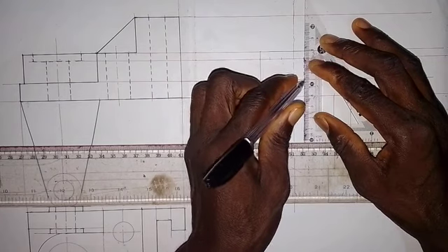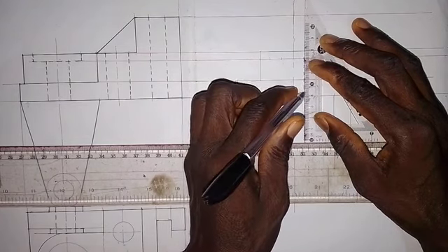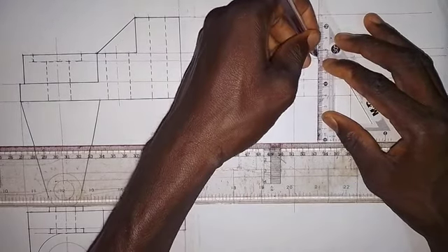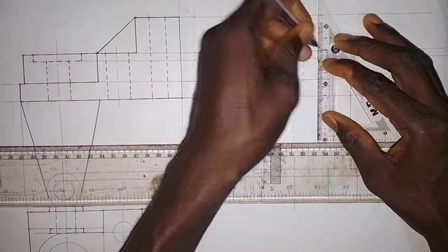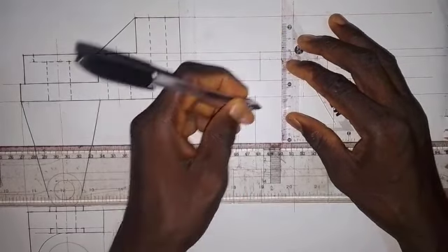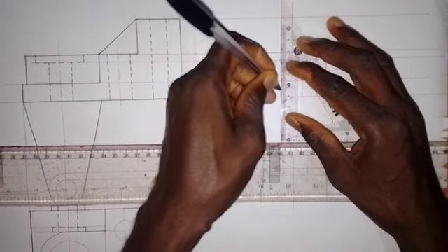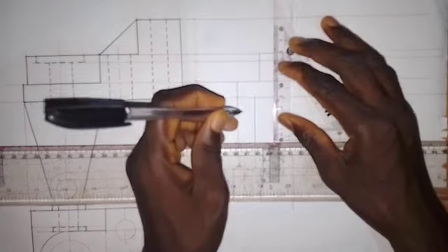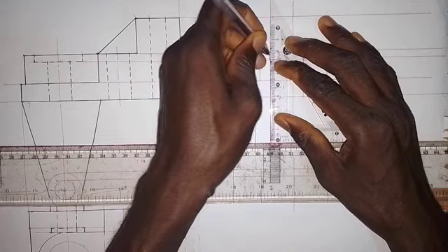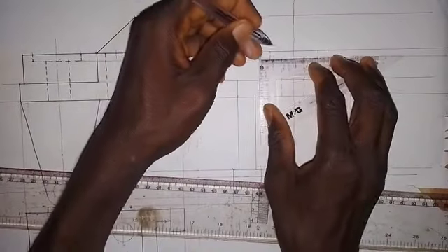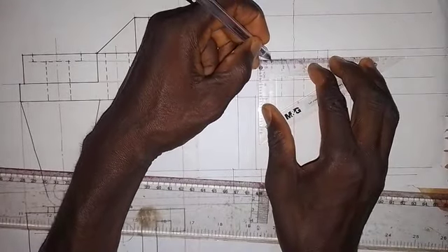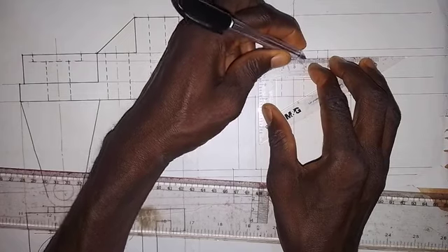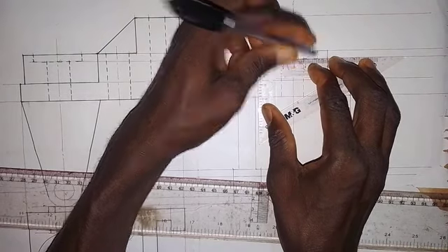So we are making this short dashes line, so coming down here like this, and this also, so make it short dashes line from here to this end here, and then this also will be drawn short dashes line from here to this point up here, and this also will be drawn short dashes from here to this end, and then so this line will be short dashes line. It is hidden from us on the end elevation. On the end elevation, it is hidden from us. So we have this. All right.